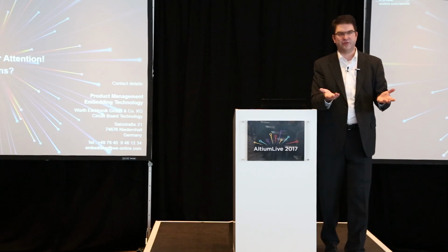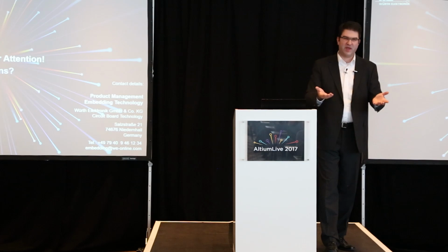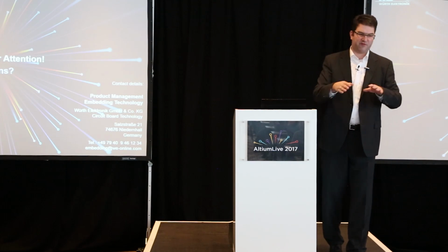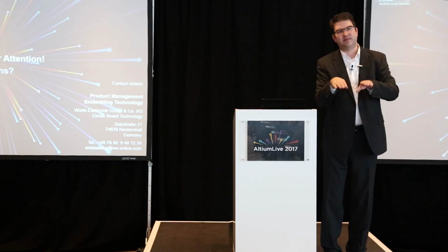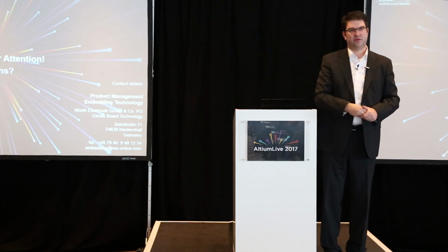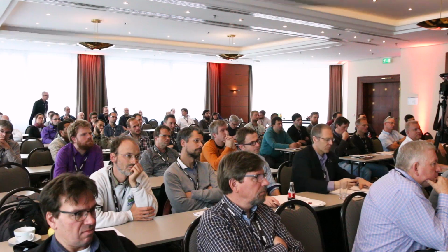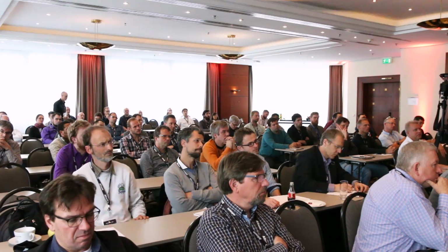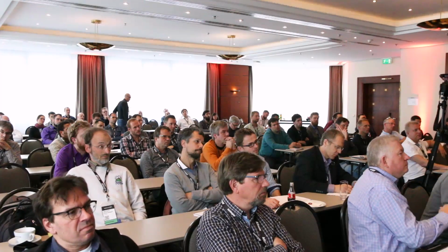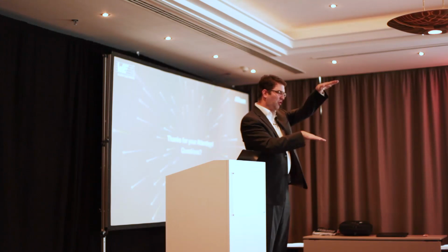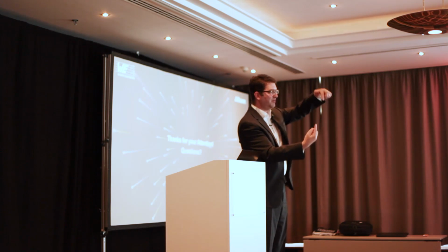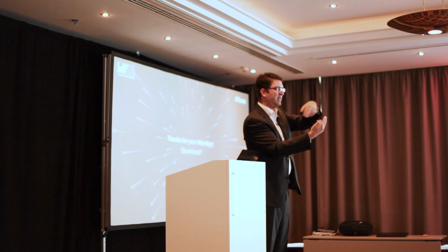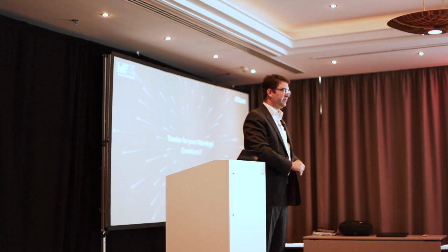So we need to have carriers, and therefore we cannot do a backside assembly of this core yet. So if you want to have multiple layers, you need to assemble multiple cores at different depths. Different depths would be possible, but from a three-dimensional planning view, it's really getting critical. We even have applications where you have two cores assembled, one going to the top, one to the bottom. And this is where step and so on comes into place, and you make collision checks and stuff like that, yes.